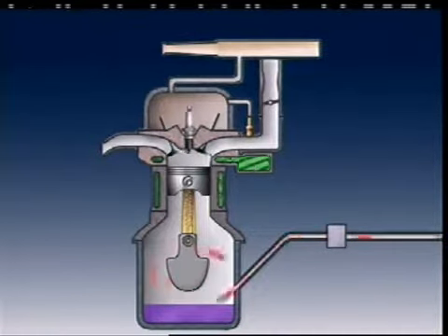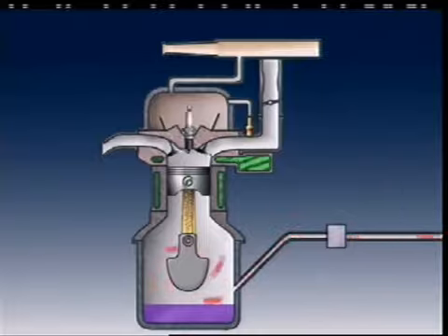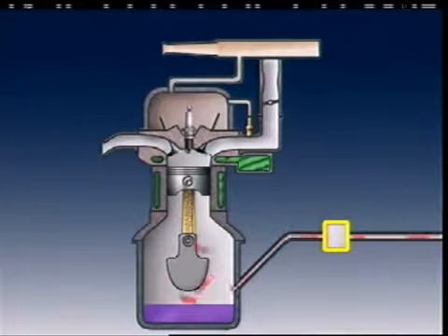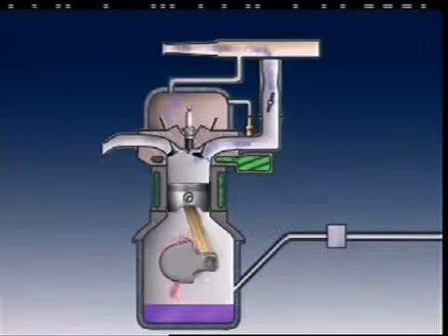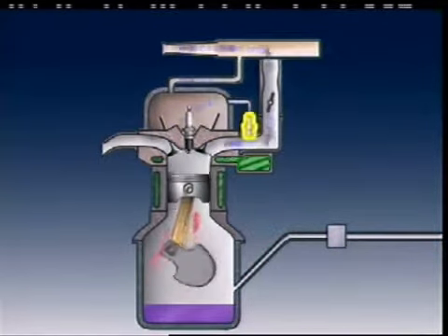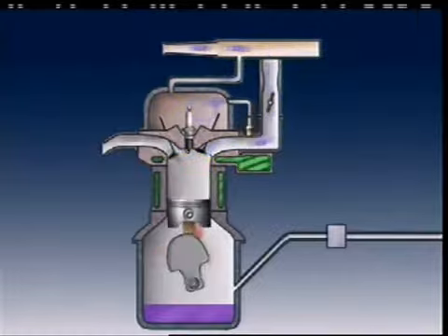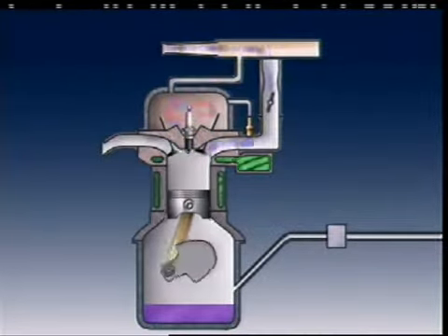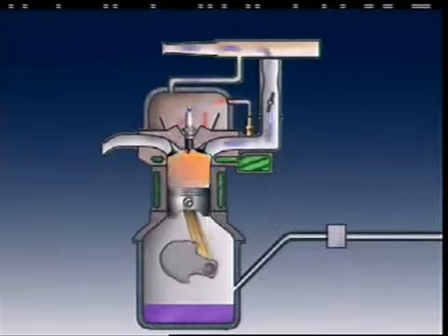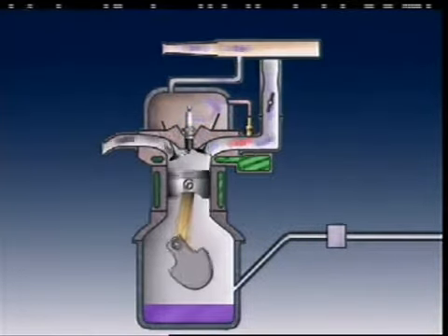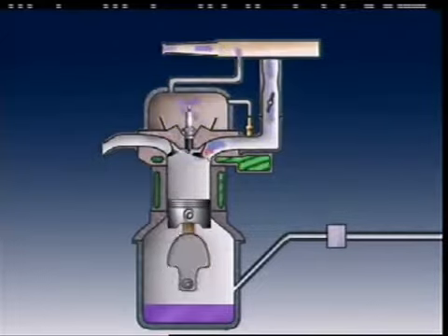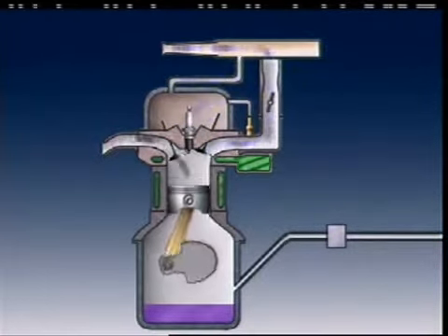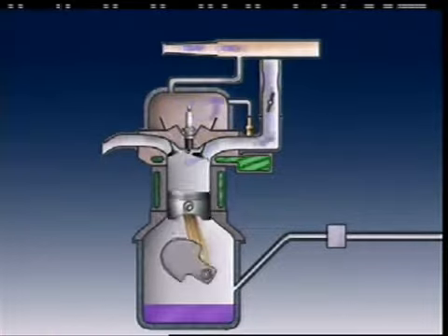When the temperature of the fuel in the tank increases, fuel vapors are forced along the vent line past the liquid check valve and into the crankcase. When the engine starts, the positive crankcase ventilation system flushes vapors out of the crankcase and into the intake manifold, where it joins with the inlet air-fuel mixture. Once in the inlet manifold, the vapours are drawn into the engine where combustion can convert them into carbon dioxide and water vapour.